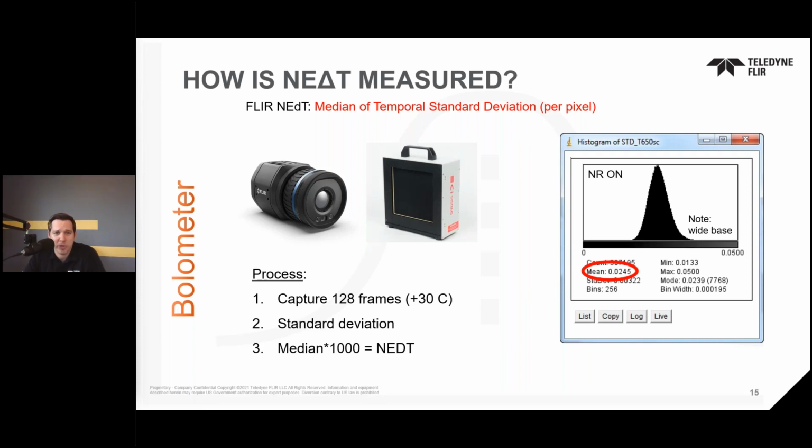If you did the same measurement process with a cooled camera, from a curve perspective, you'd see a tighter base to the curve, and that's due to a more aligned pixel response achieved from those detector types. And that percolates into the final imagery that, again, looks a lot more crisp and clear.